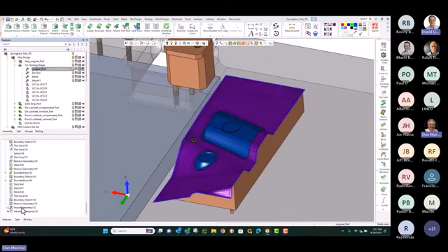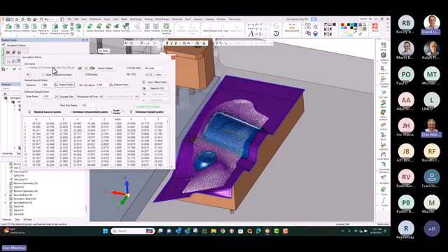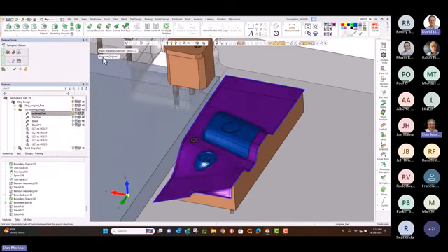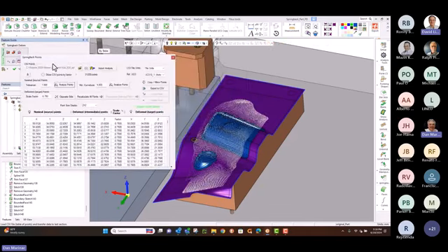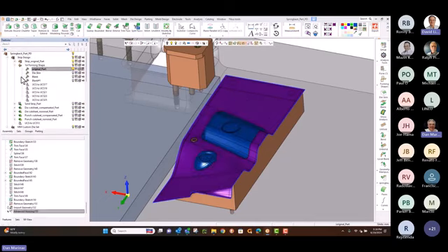Maybe we'll go back into the original part here where I've got that cut sheet. Everything is parametric, so I go right back to where I did that warping, and we'll hop over to our morphing tool where I've got my points and change the scale factor for maybe I want 3/4 of what I'm going to use here. So I'm holding back 100%. Recalculate the points. It gives me the correct vectors now. And here we just go ahead and say, go ahead and do it. If I'm confident, maybe I don't want to keep that second face, get rid of the original so that all I have now is the compensated face. That way I'm working with just what I'm going to cut with.